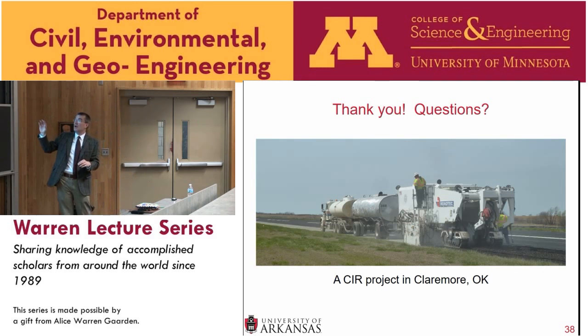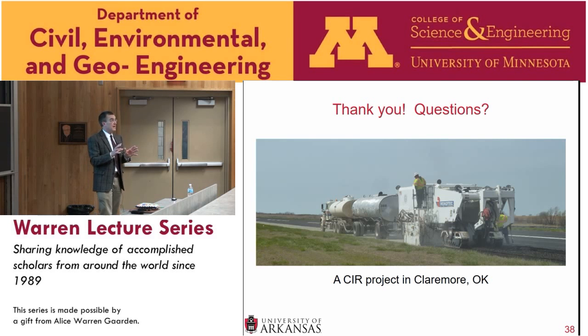And a lot of these proprietary emulsions say that it can be workable for a longer period. So if for some reason that paver is further behind than it should be, it can still pick the material up and easily place it behind there. But then another benefit is a lot of these emulsions say that you can return it to traffic more quickly, which means the water leaves the system very quickly, and that you don't want to have happen before that compaction. So I would say there's probably some gray area and perhaps a little bit of overlap, but we feel that getting it into the paver is a little different than when it's out of the paver and actually densifying. But that's something that it's always good to try and get a better grip on in our heads.